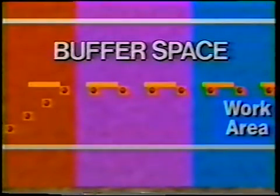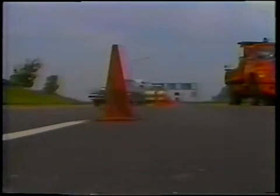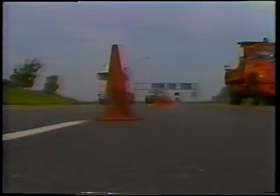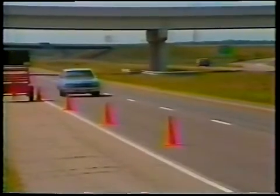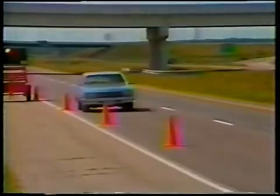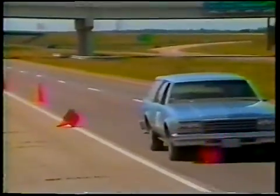The buffer space is the open or unoccupied space between the transition and work area. The buffer space provides a margin of safety for both traffic and workers. If a driver doesn't see the advance warning devices or fails to negotiate the transition, a buffer space provides room to stop the vehicle before actually entering the work area.